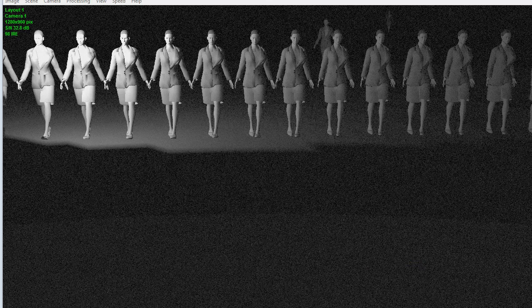Contrast of target affects the probability of its detection or identification no less than the spatial resolution. Unlike the spatial resolution, the contrast is less predictable. We can control the contrast by means of lighting and camera settings.